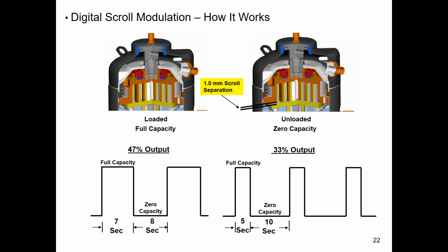Chuck asks, what about a heated suction accumulator if you have buried piping? No, nice try, Chuck, but no. If that suction line is full, the velocity of liquid refrigerant coming back in the suction line, there's no way that heater is going to make it flash to vapor adequately. It's just, no, can't do it.